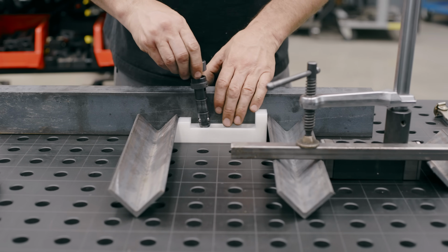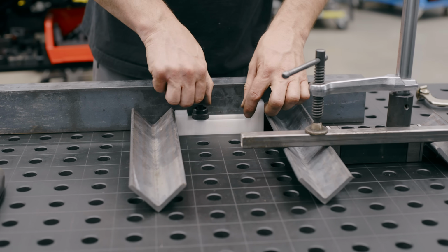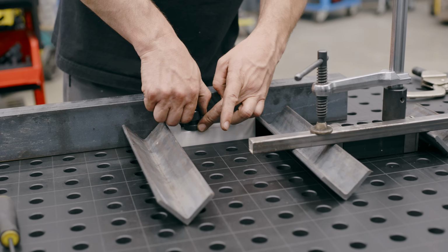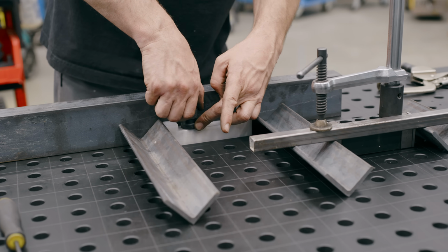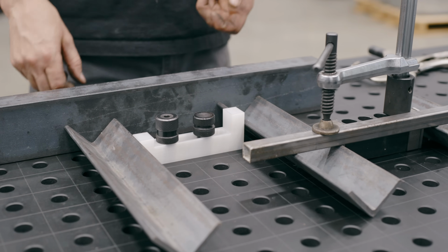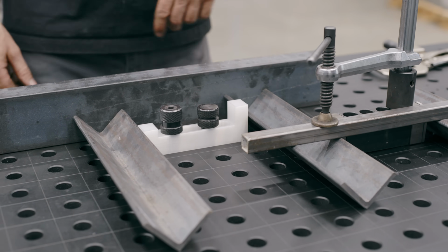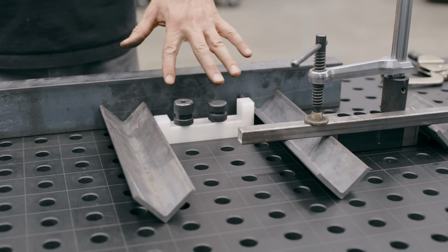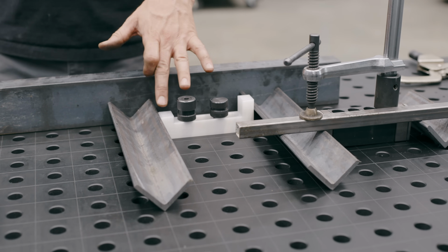So after you get one done and get it all laid out and get them all in there, you could 3D print yourself a whole bunch of these custom little fixtures like this. Something like that. That way we're away from the edge so we could weld in here. And then we can just lift this whole thing out and we'd have 2 of them. So that's the third fixture option when you have some weird stuff like this. This is pretty cool. I like this technique.